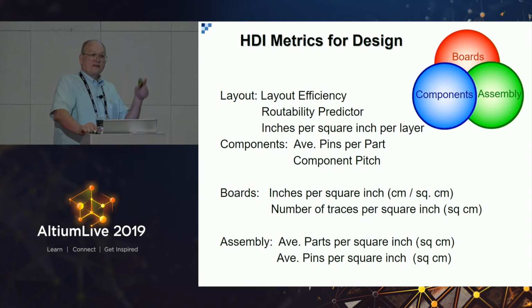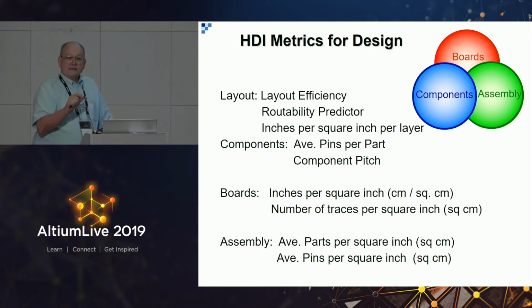When we go over the case study, we'll go from PC boards that were 6 to 8% layout efficiency to, in properly designed HDI, 18% to 32% layout efficiency, 4 to 6 times greater density on the same layer. Well, if you can put 4 to 6 times more traces and not violate power integrity and signal integrity, then you need fewer signal layers. And that's part of the reason why you have these measures of performance.